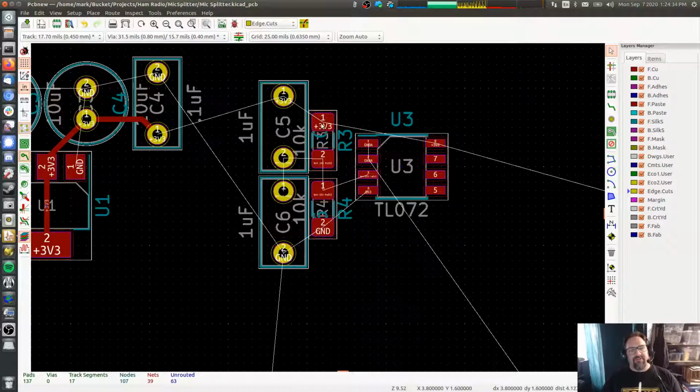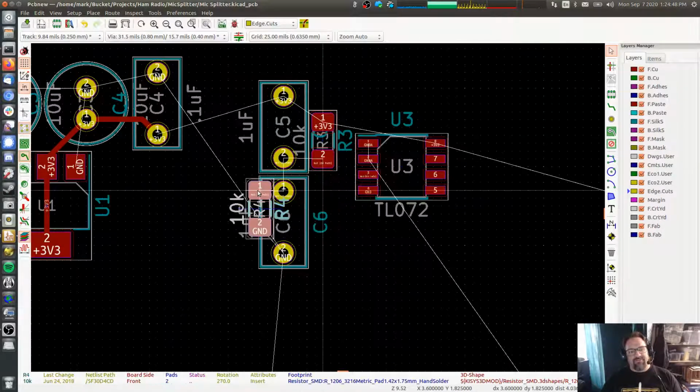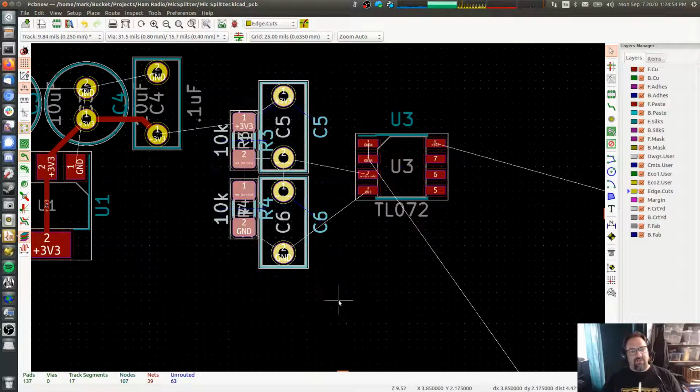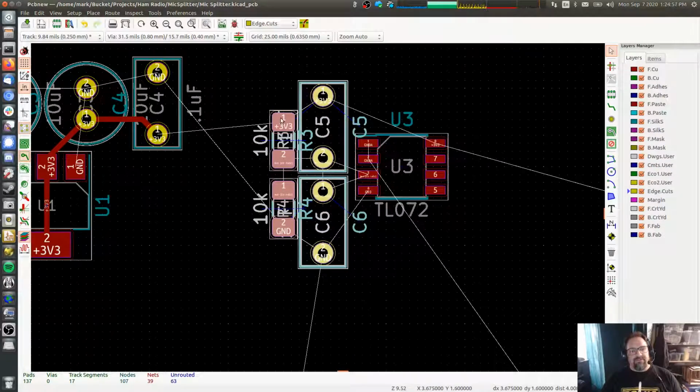So our current's going to come in from the power supply, the 3.3 volt and the ground here, and it's going to get voltage divided across these, and then we want that current to go across the capacitor pads before it goes to the pin of this. It ensures maximum filtering. So we would do this, and then move all of that closer to the chip, right? Current comes in from here, gets voltage divided, the voltage reference is established at this point here, and then it goes into these, which get filtered across, so all the noise gets dumped out to the power lines, and then it goes to the voltage reference pin on the chip.